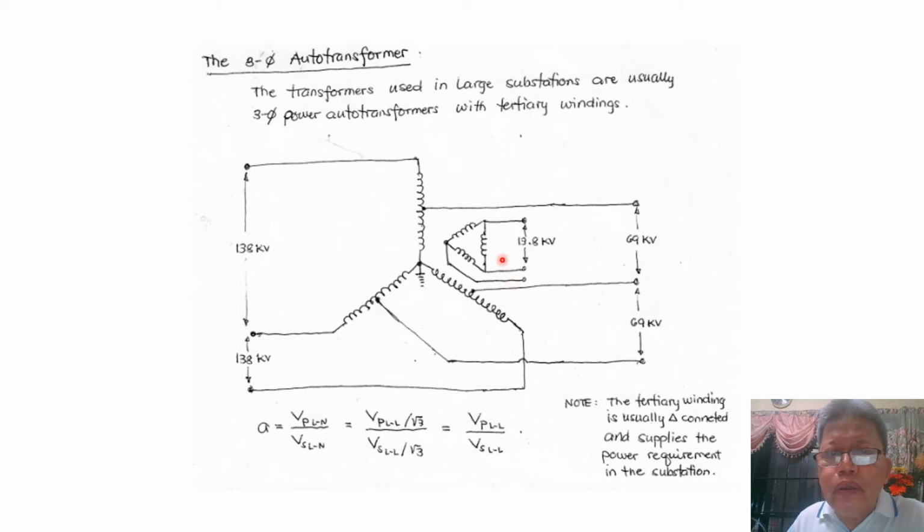Now this kind of connection is suitable for substations where our substation needs utilization voltage for its power supply, for the equipment, and for the meters or relays. So we need a lower voltage, where we can transform this into 220 or 240 using a step down transformer.